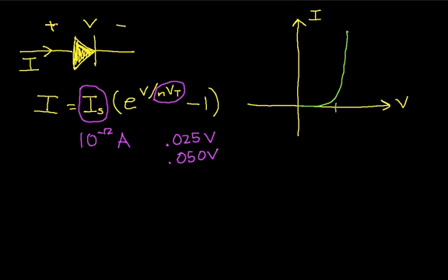This threshold voltage is typically called V sub D. It's a forward bias voltage of the diode. And again, for a silicon diode, this V sub D is typically about 0.7 volts. For a light emitting diode, this V sub D may be 2 volts or even 3 volts. So the materials out of which you construct your diode affect V sub D significantly.